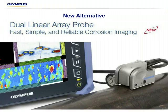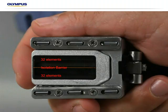So, taking the best practice of conventional thickness gauging for the corrosion world, we developed a new dual linear array probe. As mentioned before, this one follows the common methodology of a V-path, or separate send and receive transducers. Everything I've shown up to this point has been 1D linear probes where all of the phased array elements were in a single line and not isolated from each other. The dual linear is actually 2 separate rows of phased array elements. We have 32 on each side, and an isolation barrier in between so that they can't talk. One is always dedicated to sending the sound, and one is dedicated to receiving the sound. So basically it's the phased array version of the dual crystal probe.